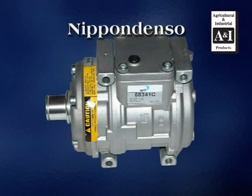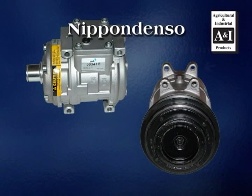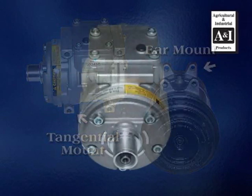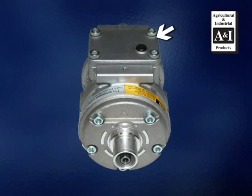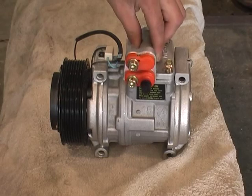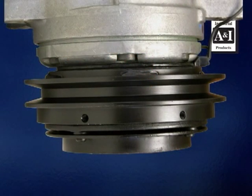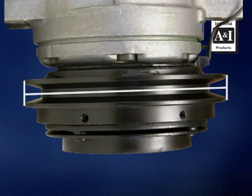The Nippondenso have 2 different style mounts. One has an ear mount, and the other has a tangential mount. Our Nippondenso compressors come with a cover plate where you remove your old manifold and install on the new compressor. The clutch is identified the same way: belt width, number of grooves, and outside diameter.